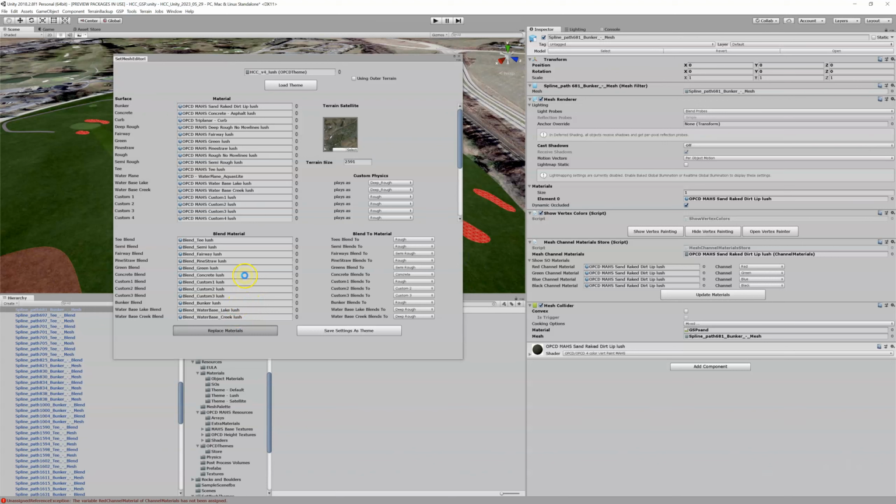It's going to take a second or two, but you can see the power of set mesh materials, which is it can replace all of your meshes. It's very handy at the beginning. However, later on, you got to be careful about using that, because if you went in and you changed a bunch of materials outside of what you have here, going back and running set replace materials again can be very problematic.